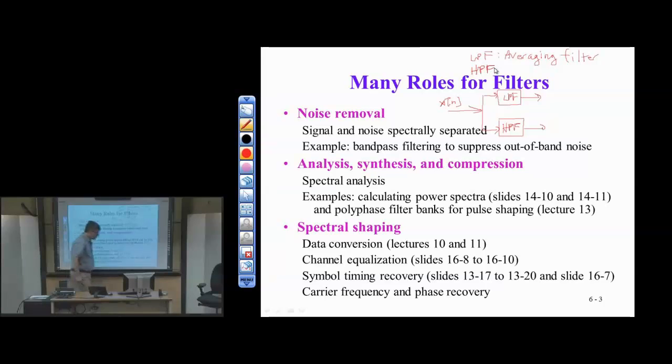Now, after we've done this analysis, we'd like to be able, in many cases, not in all cases, to combine whatever we've separated back into one signal. For this particular case, we can do it quite easily without an additional filtering step. More generally, we would apply a low-pass filter, again in the synthesis bank of filters, and a high-pass filter, again in the synthesis bank. So here we have a bank of 2 filters that does the analysis for us.